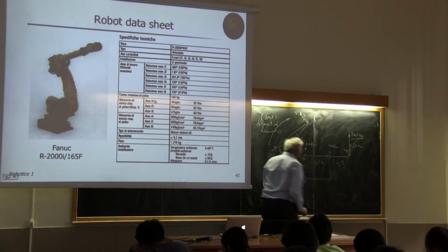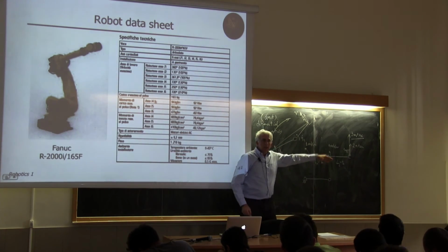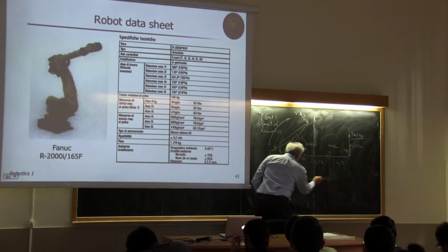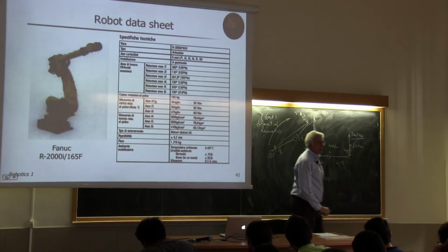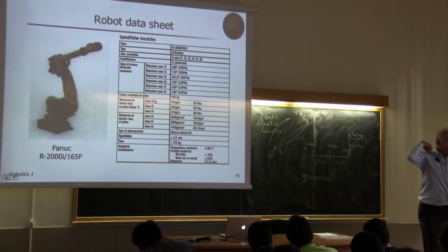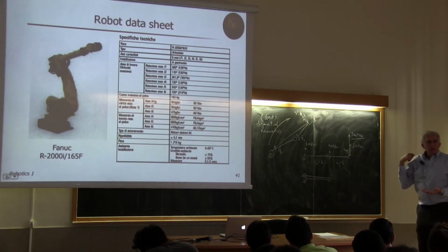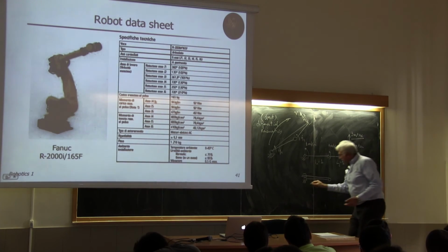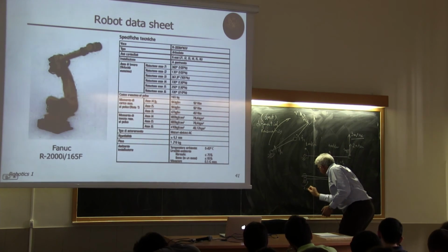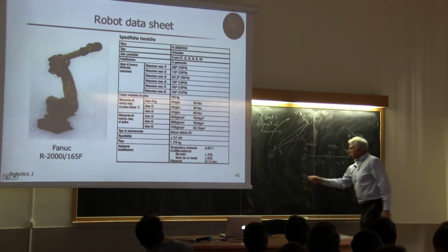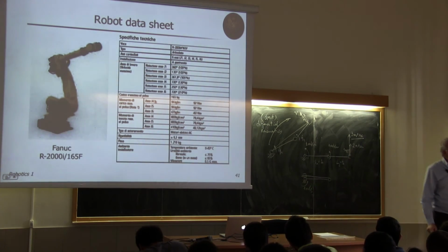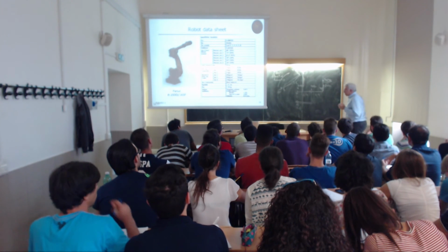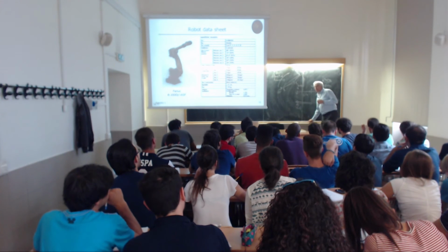where the first link is, again, horizontal, and the second link is completely folded on the first one. Since the two lengths are the same, it's like being in this configuration. And now I'm giving the same speed to the joint. Now, if I'm giving 1 radian per second to this joint, what will be the end effector velocity? 0.